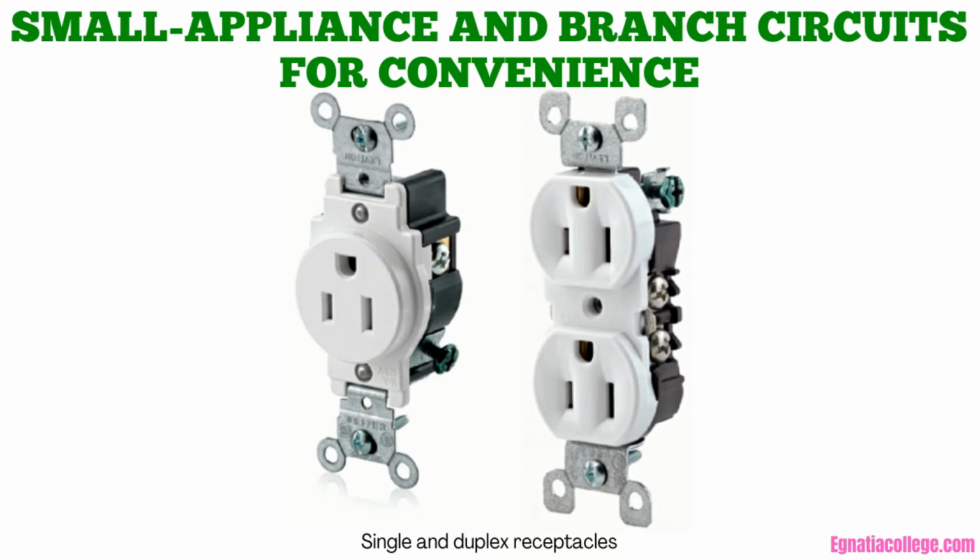The CEC requirements for small appliance circuits and the spacing of receptacles in the kitchens of dwellings are covered in Rules 26-720 and 26-724. This was discussed in detail in Unit 4. Highlights are: a microwave in its own enclosure gets its own circuit, and so does a refrigerator. These small appliance circuits shall be assigned a maximum load of 12 amperes each when calculating branch circuit conductors.